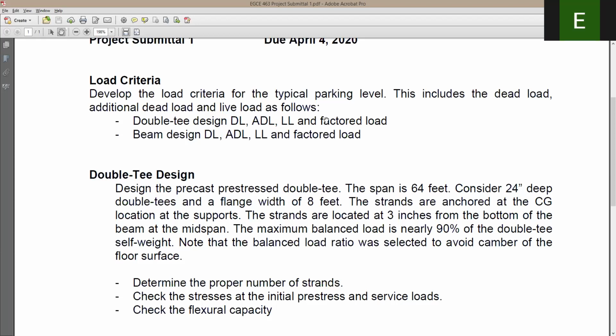Will the live load be in the PCI or no? No. The live load is going to be in the ASCE 7-16 or in the CBC. Do you want to Google it now, parking structure live load in California Building Code, in CBC? What does it say? 40 or 50?